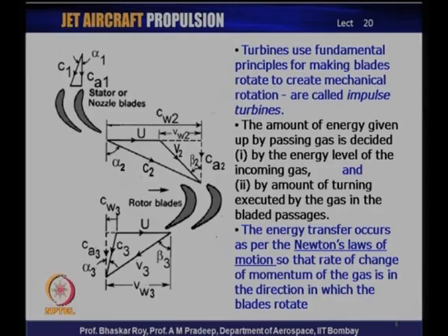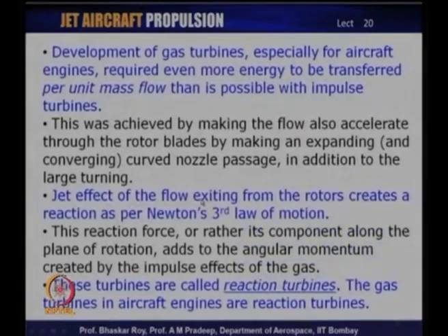So, we have two forces now acting on the rotor: the impulse force due to the turning of the fluid through the turbines, and the reaction force due to the acceleration of flow through the turbines. The two of them together create what is known as reaction turbines. So, all the aircraft gas turbines are indeed reaction turbines.